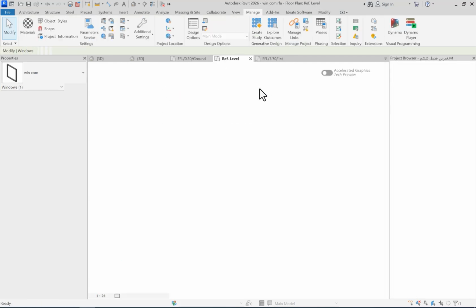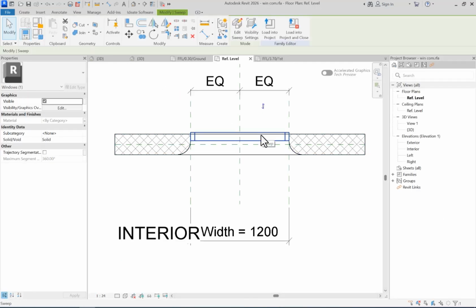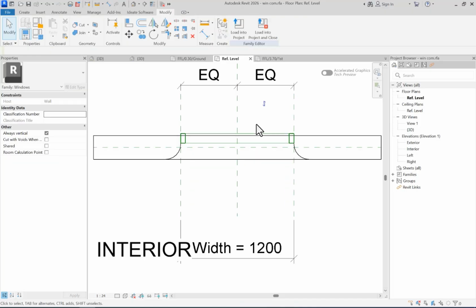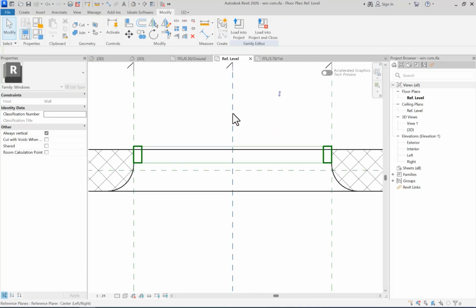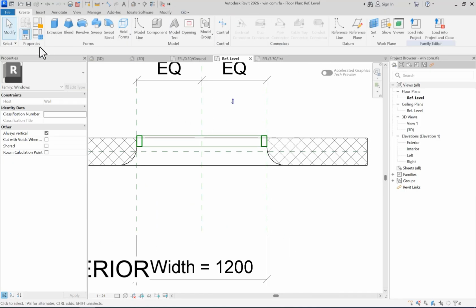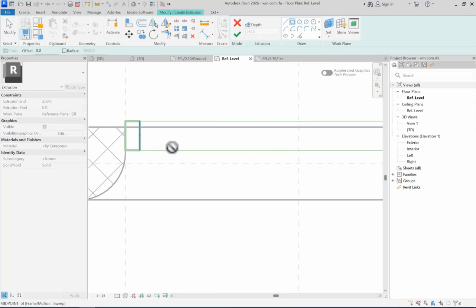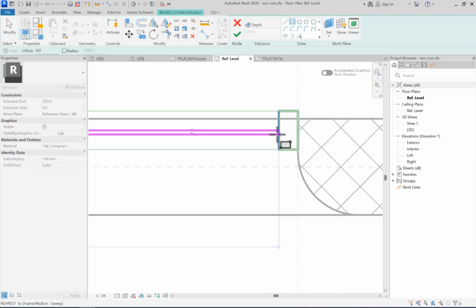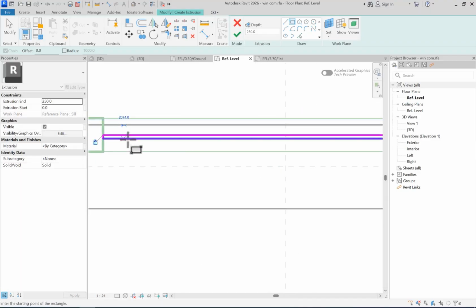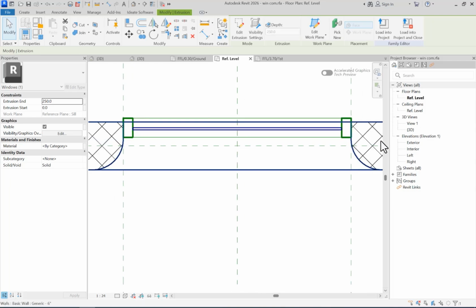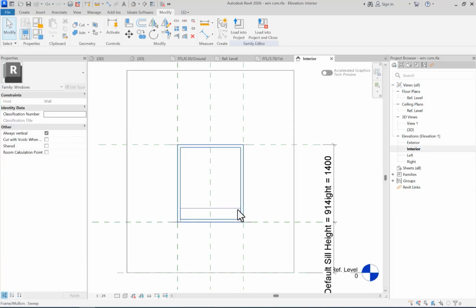Let me elaborate, it's quite simple. Take a look at this, guys. We can easily select an element or a part or something and then specify the exact subcategory. For example, frame mullion. Now we can easily and separately control the thickness or the line weight. Now, let me set something here representing the glass. I'm also going to lock this down. Right back to this view and specify the height.